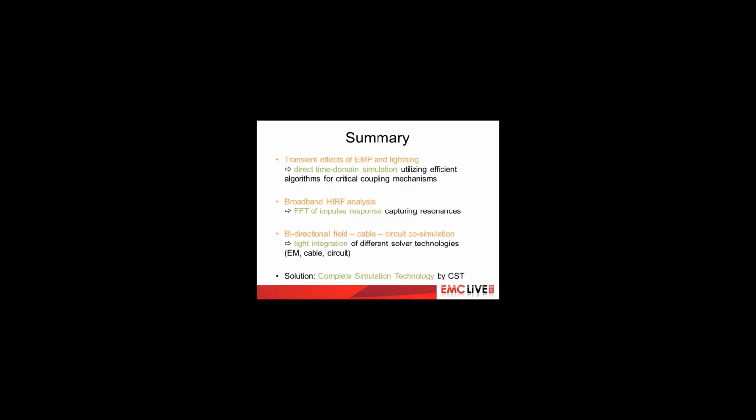Okay, I'd like to summarize the presentation. So we've seen simulation of the transient effects of EMP and lightning. Direct time domain simulation is very powerful for solving this and capturing all the transient effects. And we can utilize efficient algorithms for critical coupling mechanisms, such as the composite materials and the seams in the cables. We also saw how broadband HIRF analysis can be simulated by calculating the impulse response of the aircraft and then using Fourier transformation to look at all the spectrum and all the resonances.